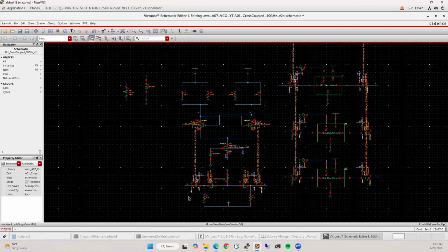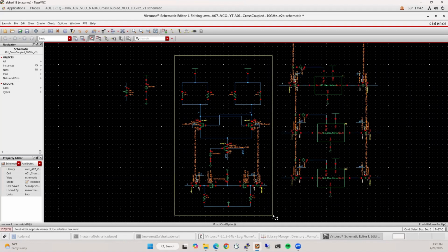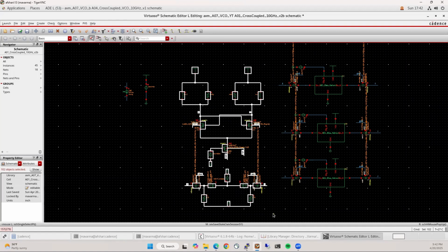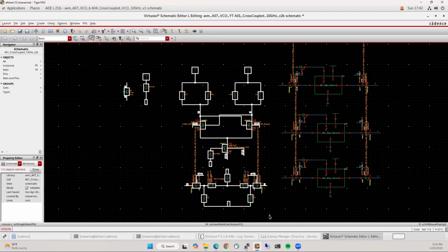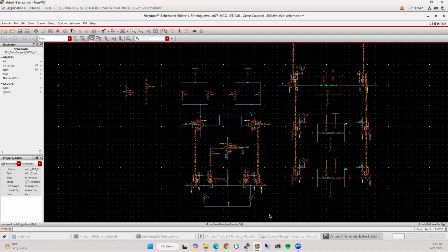So once you have the ideal load to maximize, let's say, output power, then you can kind of design interstage matching to the next stage. So following this, I'll discuss maybe frequency doubler design. That's probably the next stage that will come into this chain. Moving forward, I might not use this discrete tuning. I'll just stick to continuous tuning, just to keep it simple. Discrete tuning we might revisit when we do digital PLLs sort of in the far future. As of now, this is probably enough because this gives us probably enough bandwidth for the automotive band at least. Okay, so hopefully you're excited about all those videos to come.